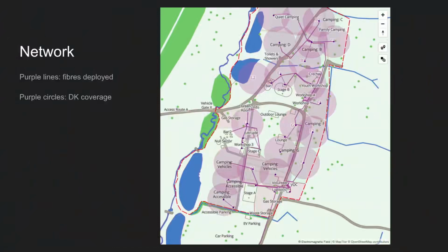This diagram comes from the same CAD system as was used for power distribution. Lots of shared development there. Purple lines are the fiber that goes across the field, from central places to all the data flows. The circles are roughly 50-meter diameter circles around each data flow, being 25 meters, kind of a rule of thumb. You can't really expect people to bring longer cables than that. So data flows are spaced out on the field so that the circles just almost overlap.